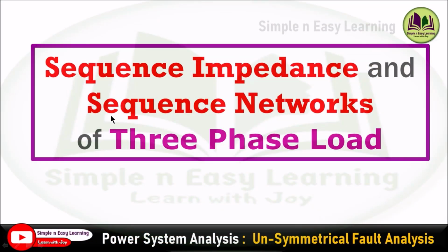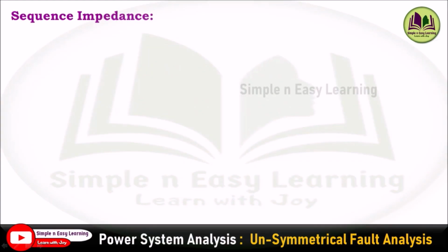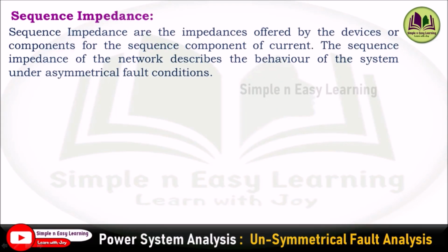Sequence impedance and sequence network of three-phase load. Sequence impedance definition: the sequence impedances are the impedances offered by the devices or components or circuits for the sequence component of current. The sequence impedance of the network describes the behavior of the system under asymmetrical fault conditions. There are three sequence impedances: positive sequence impedance, negative sequence impedance, and zero sequence impedance.